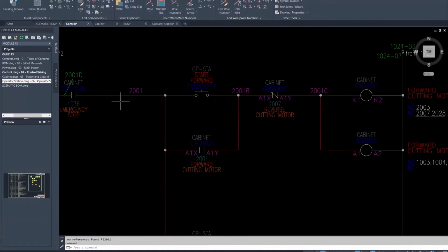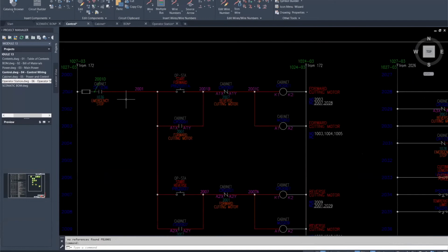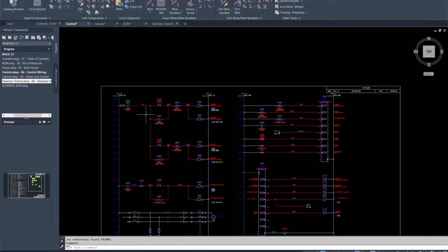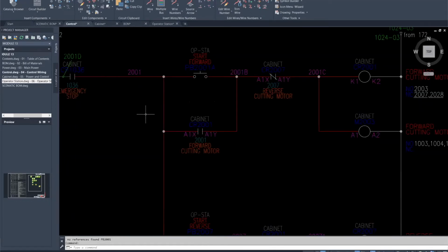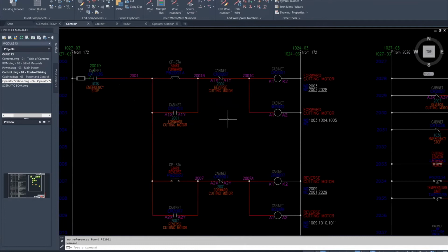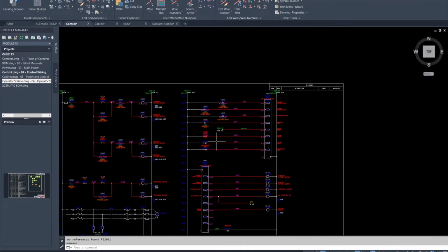And it says, okay, are there any other components that are related to that? If you're going to erase that, and I have another one that's attached to it, should I erase that way? You can see it got rid of that component and healed the wires, fixed my schematic, and renumbered the wires. It would take that off of my bill of materials, and take it out of my panel. If it was in my panel and I ran an error check, I can't erase that without it taking it off my panel. So that's the beauty of that. Okay, I go, where's that one used? So that's kind of building and working on schematics.